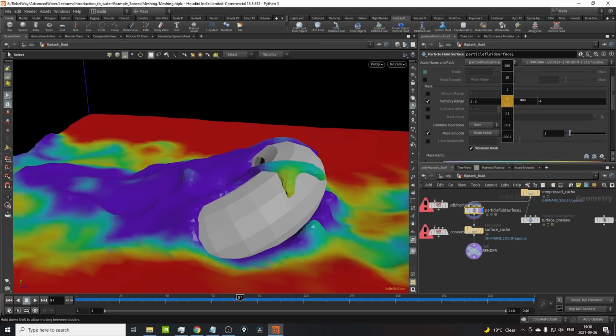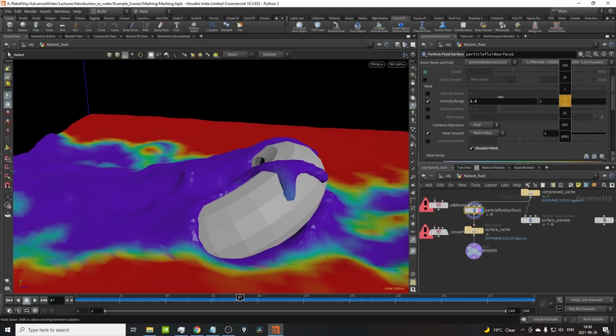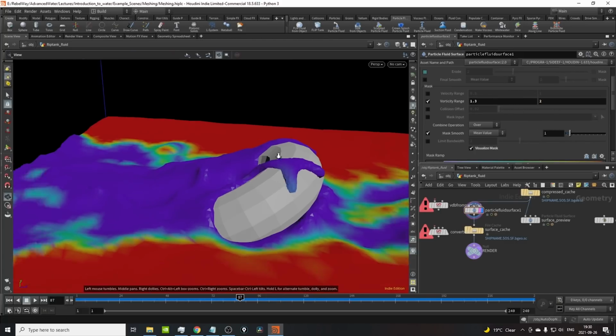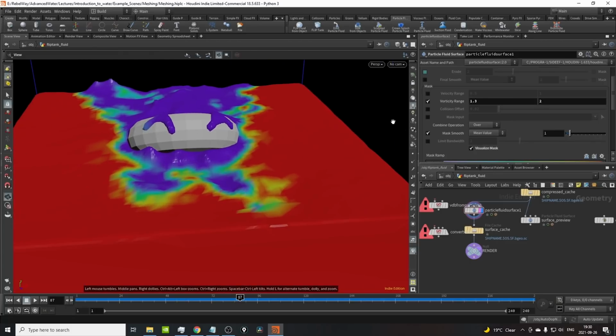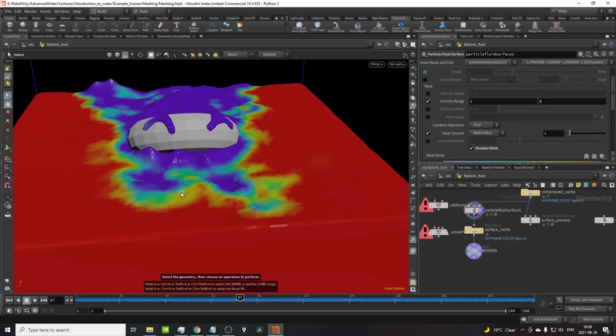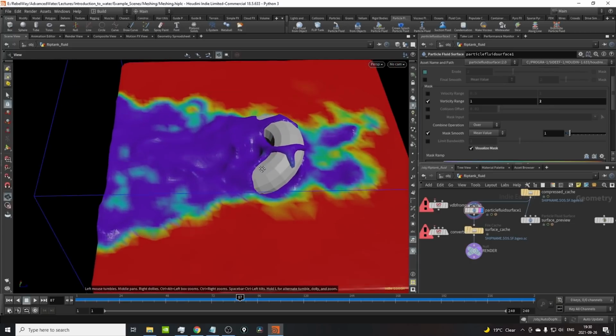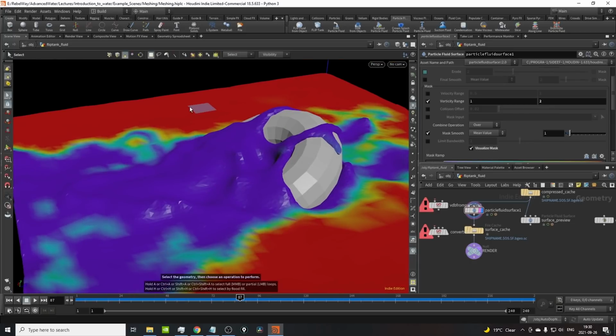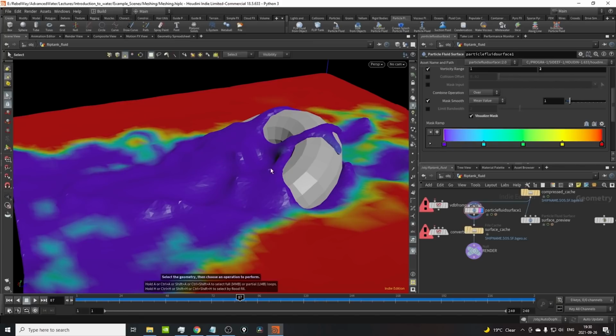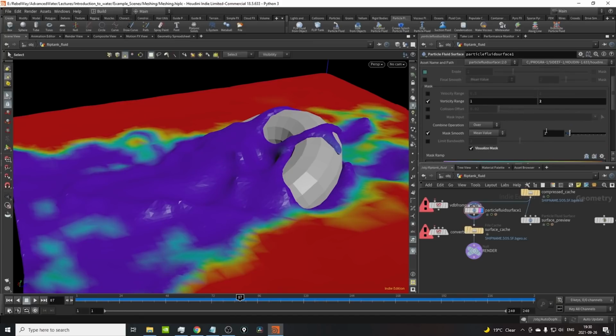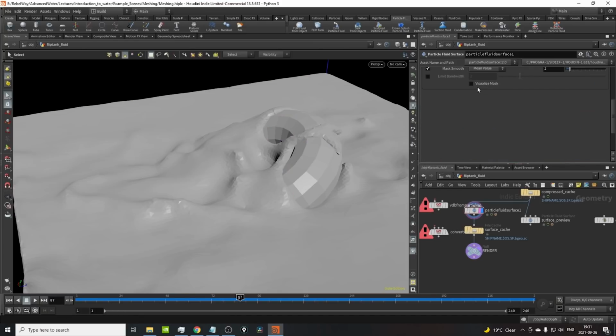So we can just say, well, everything with a 1.3 in vorticity should get it. But as soon as we reach 2, for example, I don't want to do any more smoothing. And go 1, so it's feathered a little bit more. And now we know everything red gets blurred. Everything in this purple, violet color does not get blurred at all and does not get smooth.